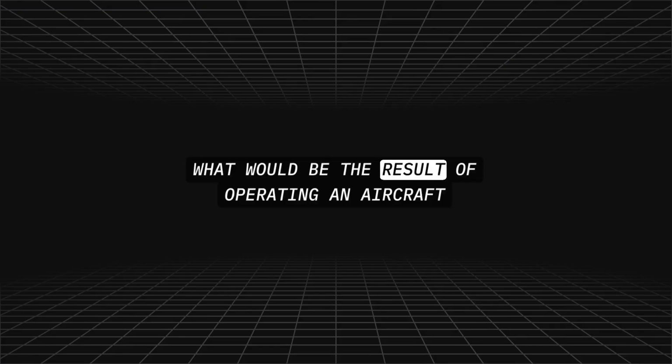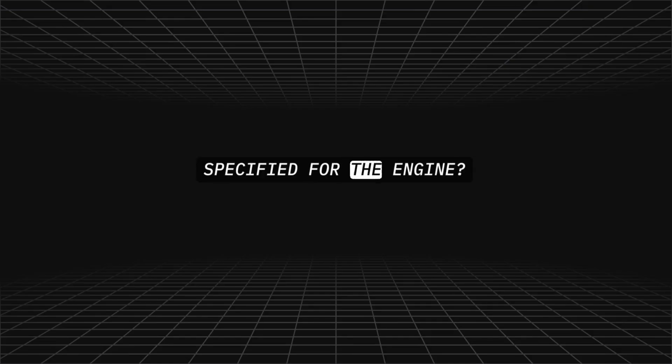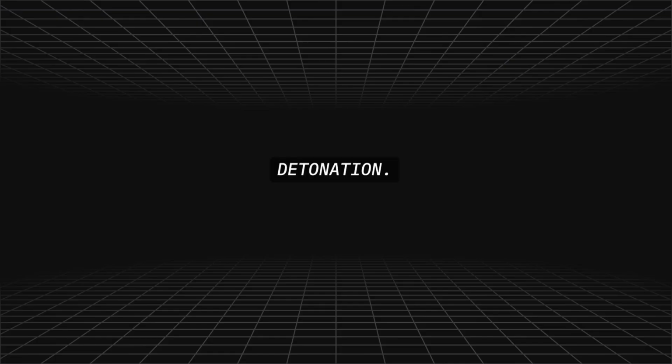What would be the result of operating an aircraft reciprocating engine using a lower grade of avgas than that specified for the engine? There would be a loss of engine power, efficiency, and possible detonation.